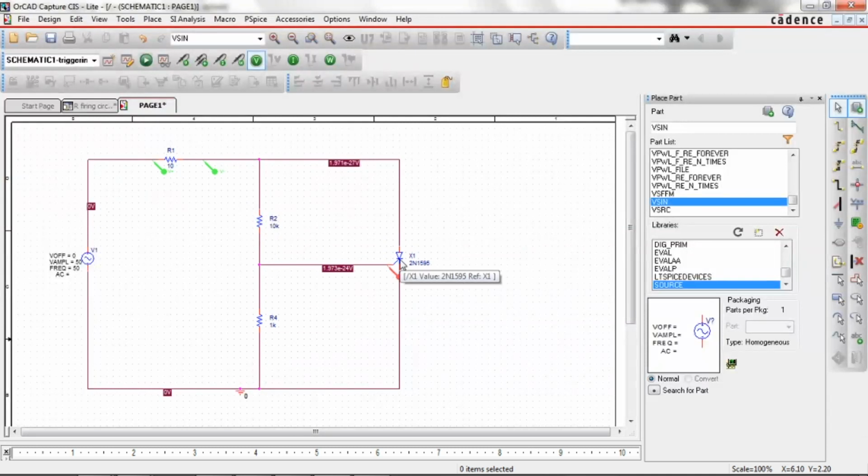That's the reason, from 1.9 milliseconds onwards till 10 milliseconds. My power frequency is 50 hertz, so the period is 20 milliseconds and the half cycle is 10 milliseconds. So here the SCR will turn on at 1.9 milliseconds, and it will continue till 10 milliseconds.